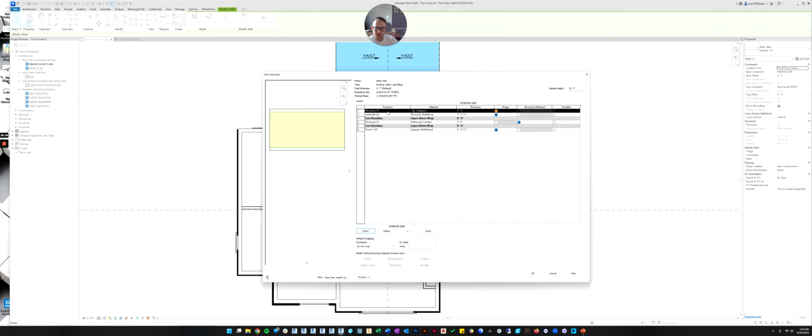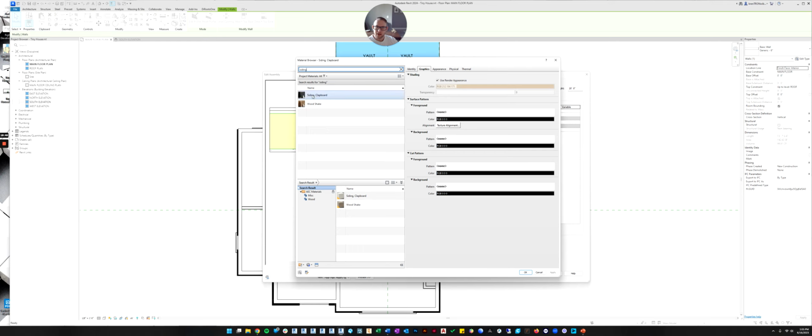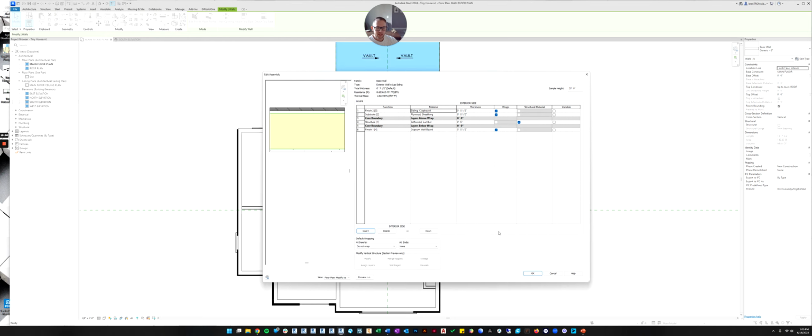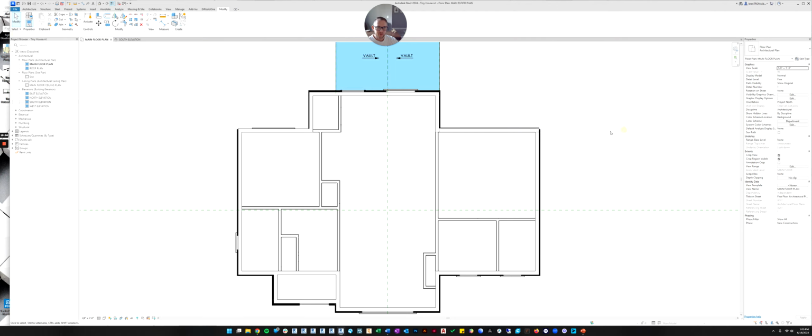So we're going to insert one more layer, and this is going to be the outside finish. So we're going to call it finish 2. And siding, depending on what product you're using, it varies, but we'll just say it's another 1/2 inch of siding. So that adds another layer. And now we need to pick the material. So let's just see if there's siding already built in. And yeah, they do have a siding. Okay, we'll click OK.